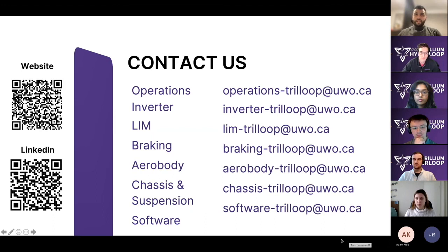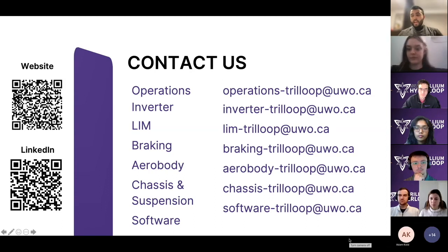However, given that the flywheel is moving at almost 1,000 kilometers an hour, there is a lot of convection heat transfer occurring, which removes a lot of heat from the flywheel itself. The maximum operating temperature of the aluminum alloy is pretty high, somewhere around 750 degrees Celsius. So it won't be a concern, given that we have a lot of convection occurring and also conduction through the diameter of the flywheel. So it should be fine.